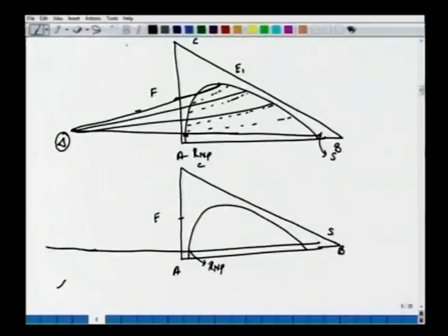We are looking for del min. What is the minimum amount of solvent when the operating line coincides with the tie line? So all we do is find that tie line which, if we extend, will intersect the line here. So now we have the amount of solvent corresponding to this del min, which will give us an infinite number of stages, because now this is the same operating line, which is coinciding with this tie line.